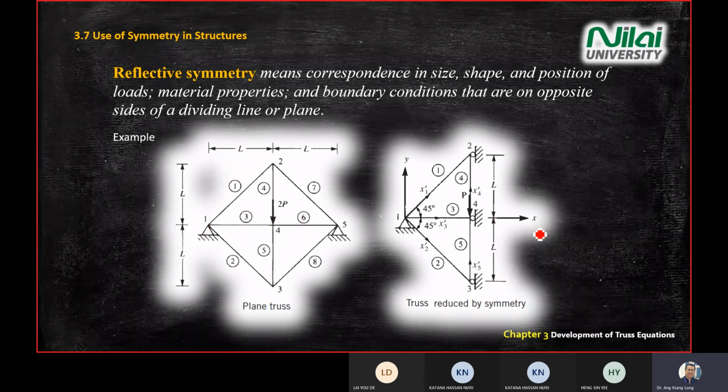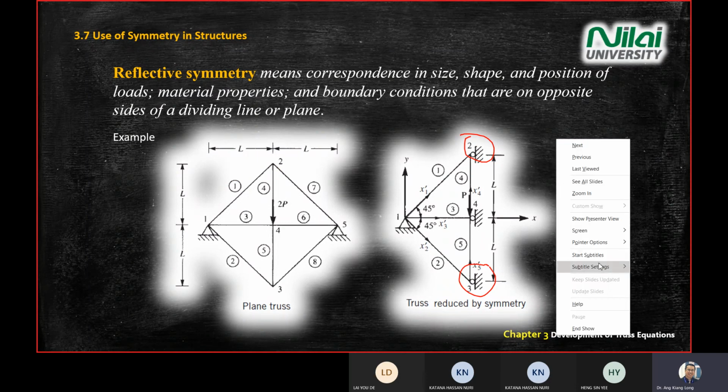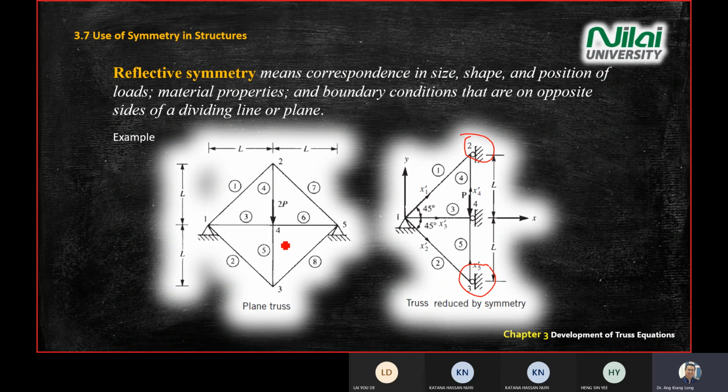The procedure is still the same. For point 2 and point 3 also the same. You convert to a ball bearing constraint where you can see that point number 2 will also move along the vertical axis only. For this case, because there's only one force.